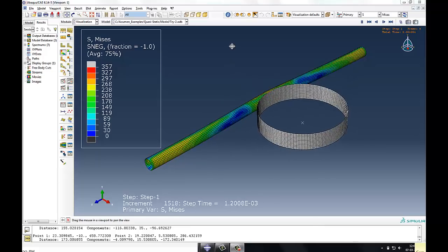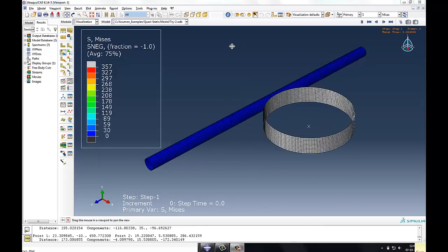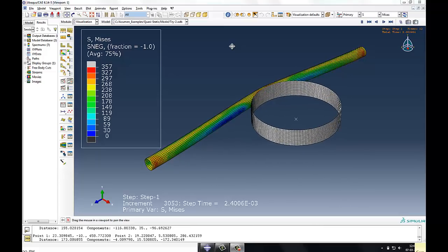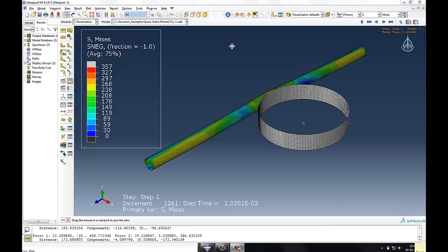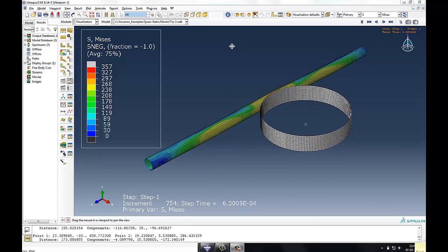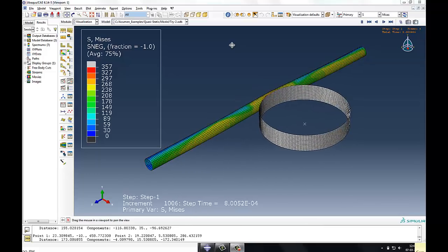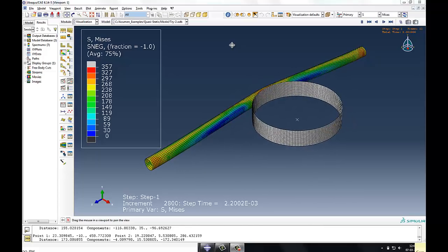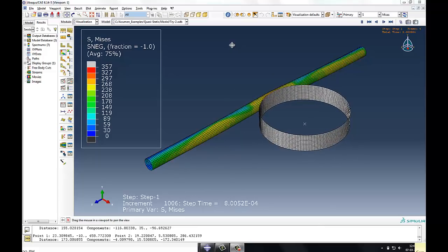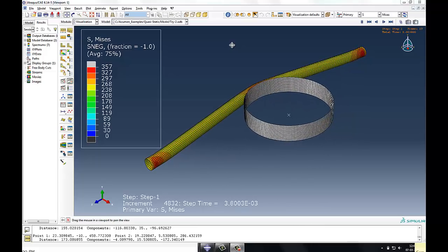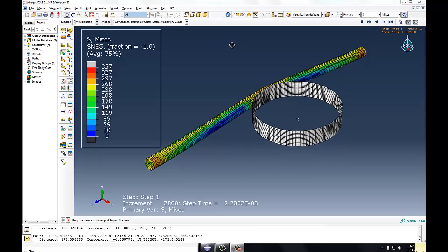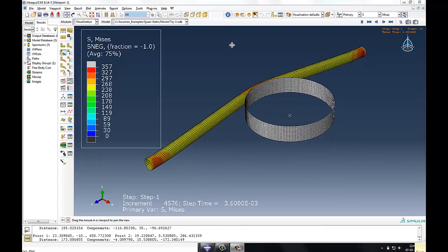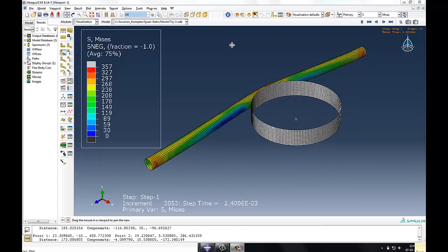The performance is evaluated in terms of the load offset deflection results, wherein it is expected to deform, and while deforming it should also have the ability to absorb the impact energy. This simulation is carried out in a slow rate of application condition, that is a quasi-static condition, wherein the inertia effect will be negligible or should be zero. And when you say this, the kinetic energy of this simulation will be less or tending to zero.